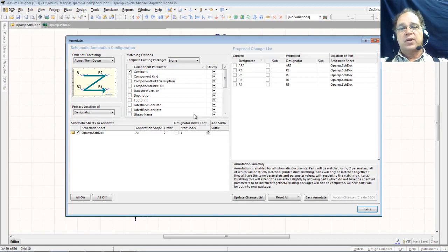So if I have a bigger project and I have, say, 3 sheets in there, I can start sheet 1 on 100. I'll have another one here that'll say op amp, different sheet number, start on 200, another sheet number, start on 300. If I do that, when I place my parts on the board, I can tell when I'm looking at the PCB which sheet the schematic part came from. If the part starts with R300, 301, 302, I know it came from schematic number 3.